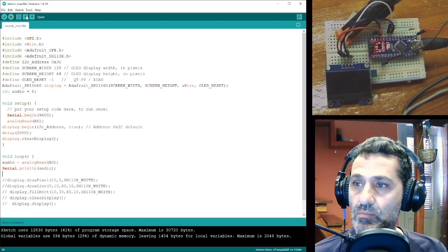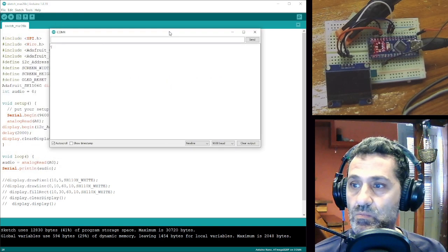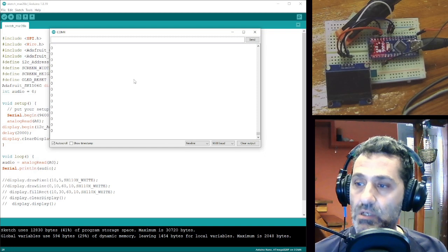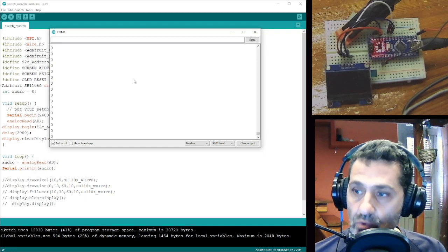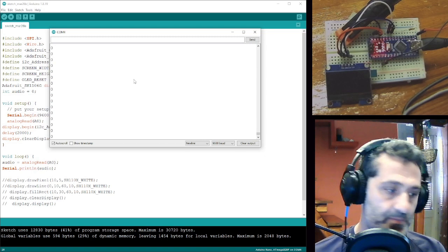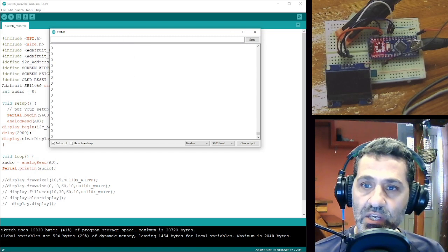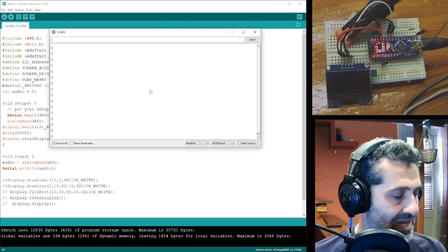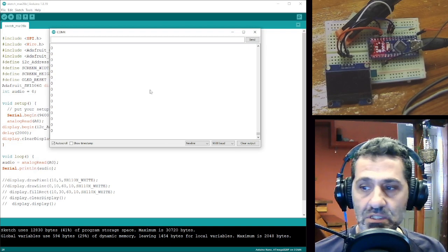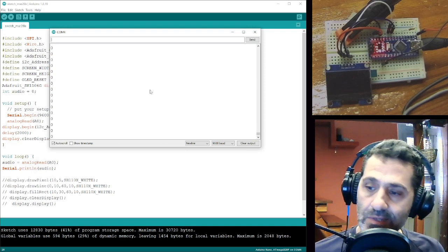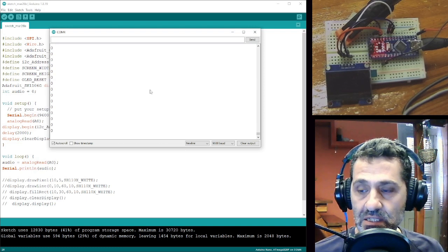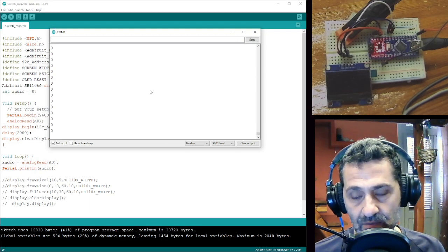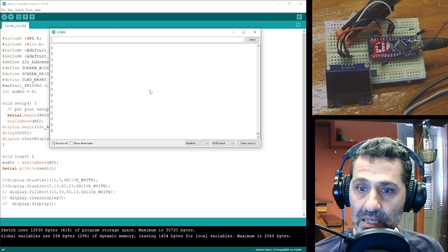Okay, serial monitor. So we get zeros. That means, you see, we get here zeros. Getting zeros means the analog input of the Arduino is not reading anything. Okay, now I will try and see why it is not reading anything and come back.